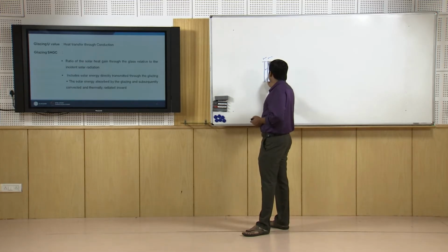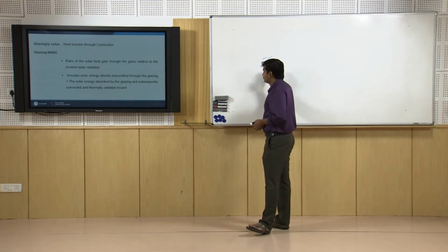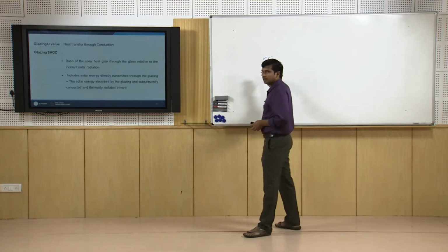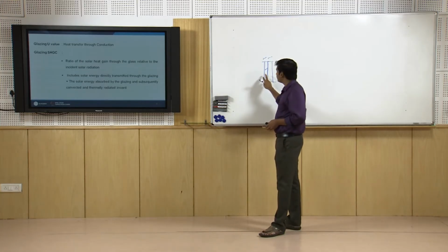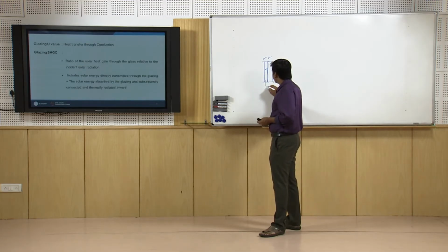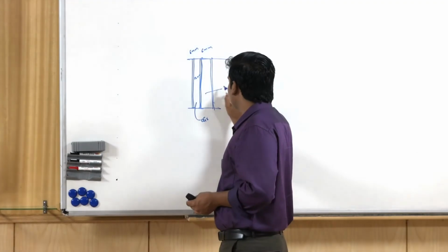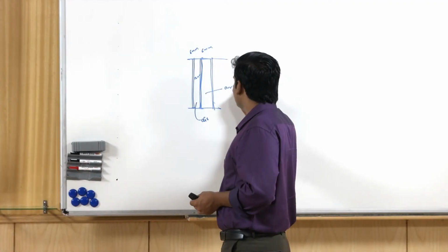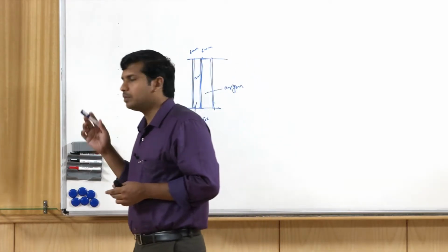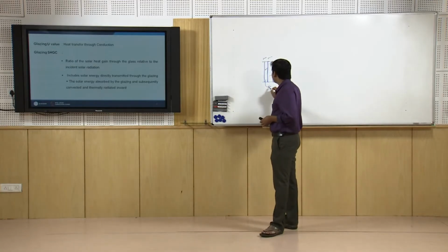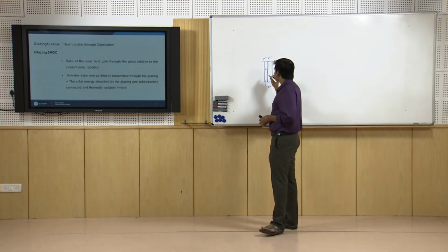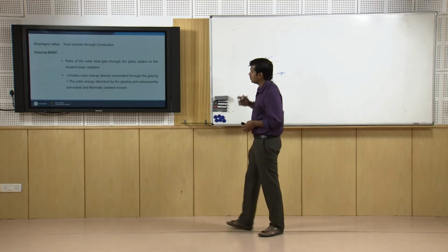Further, with each next layer, apart from the film coefficients outside and inside, the more layers, or the thickness of glass itself, or the type of infill, whether it is air or an inert gas like argon, the U value reduces considerably. Air filled versus argon versus a vacuum insulated system, the U value comes down considerably.